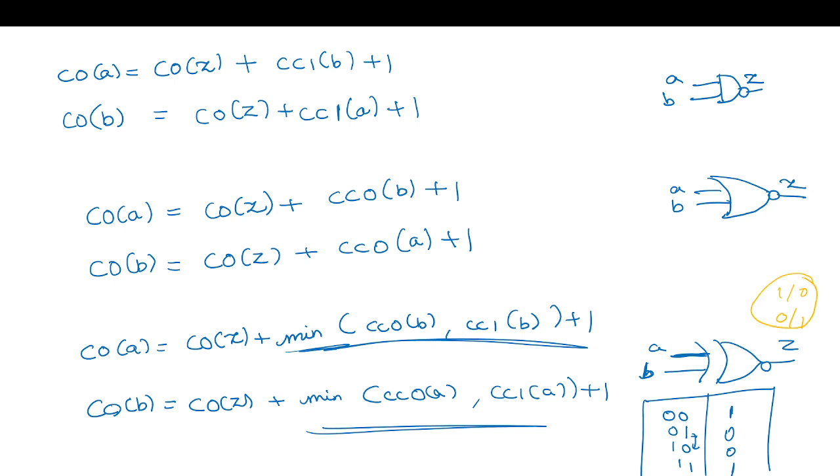Both are fine. It should be D or D bar. Same for XOR also. We want the output to be either D or D bar. So if we have a D here, it will be observed as D bar. This is fine, but it should not mask to 0 0 or 1 1. That is not allowed.